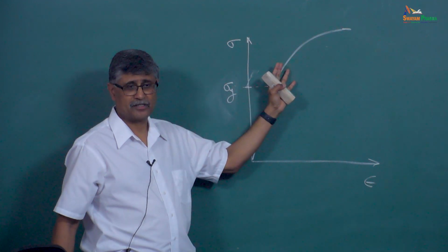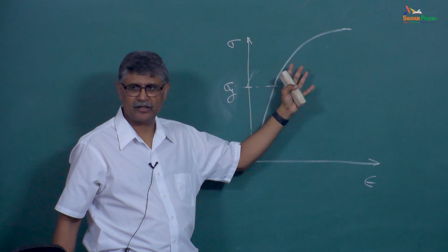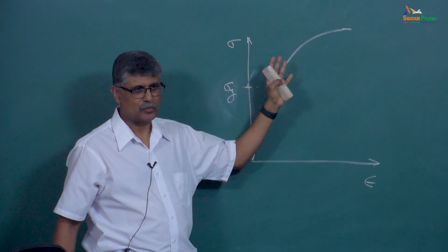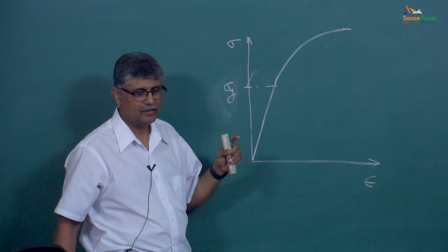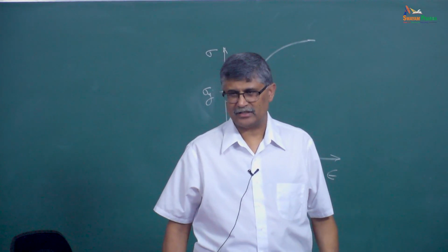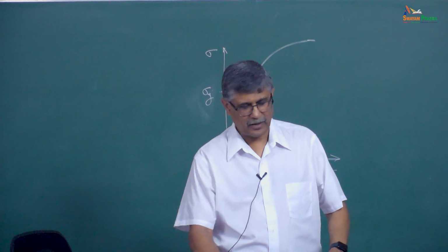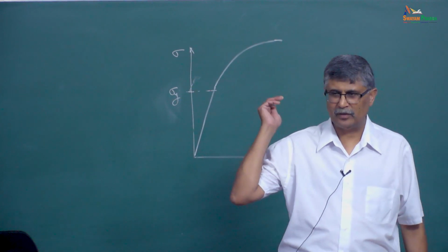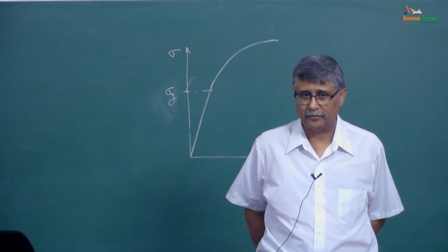Yes, it's plastic deformation. But what is this increase in flow stress with strain? Strain hardening, or work hardening, or strengthening, right? So this is the strengthening that the slide is talking about. The strengthening, and let's ignore what's in the parentheses for now. Or maybe we spend a second here. What is happening when a material is undergoing plastic deformation? What is happening inside the material?